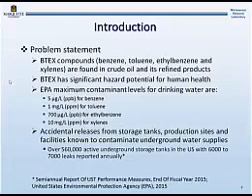So the background for this investigation is really groundwater monitoring for BTEX compounds, which are listed here. So they are found in crude oil and its refined products, and therefore are good indicators for fuel and oil spills. BTEX has significant hazard potential for human health, especially benzene, which is listed as carcinogenic.